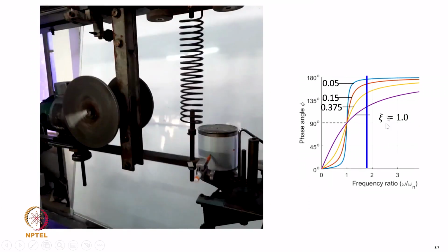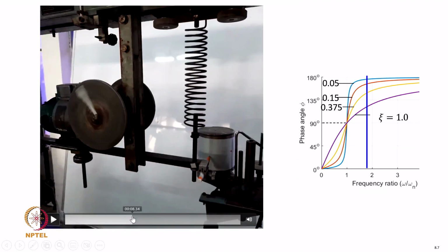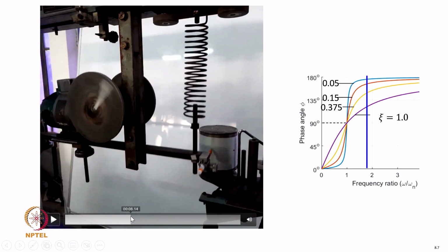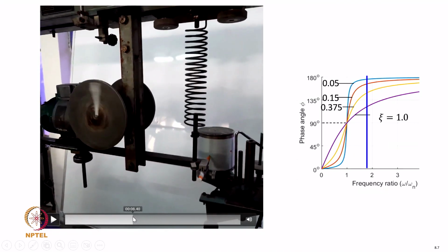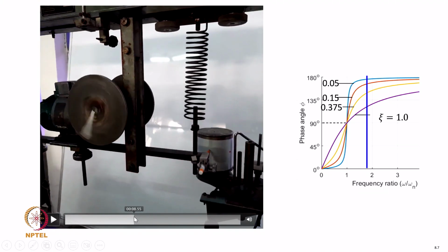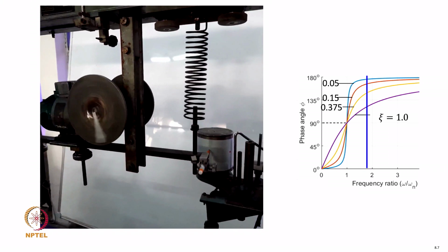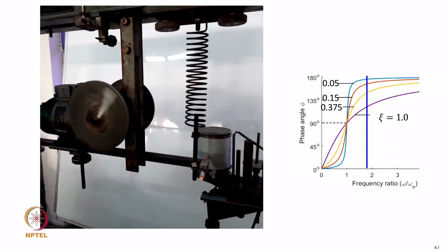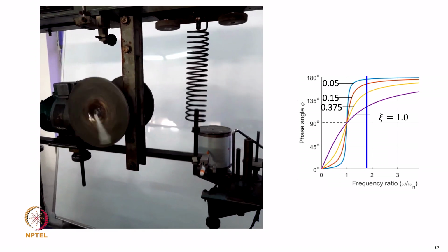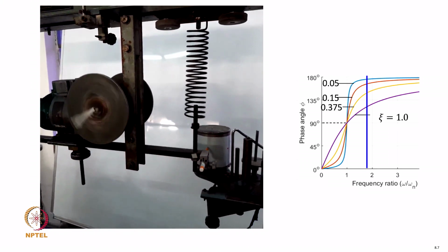In the second case, I am operating here, which is post critical or post resonance. So, I will also play out this one slowly. Maybe you can see, as the unbalanced mass, which is represented by this white strip, goes down gradually, the pencil is going up. The mass is going down, and the unbalanced force is going up, the pencil is going down. Then as this is going down, the pencil is going up. So, you can correlate.